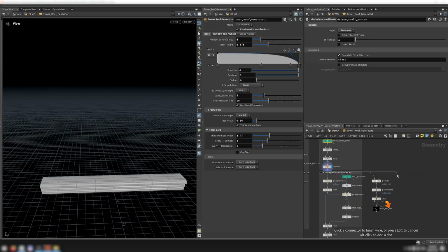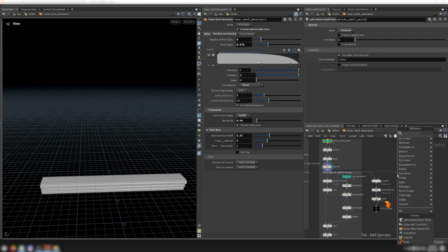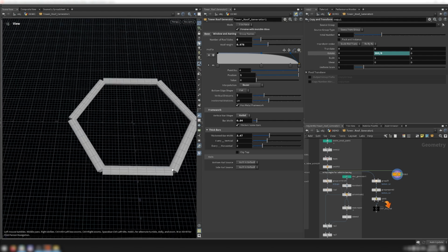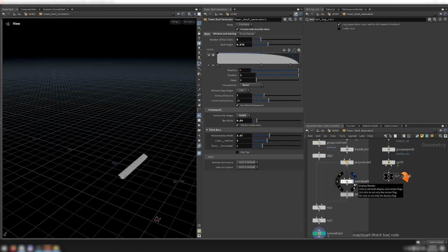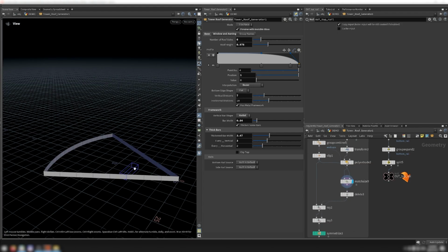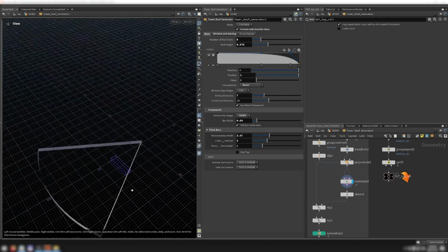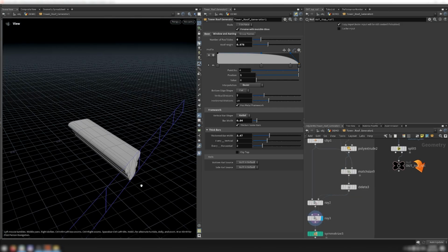If you just sweep the bottom rail, the module looks fine on its own, but when it's assembled, it doesn't line up well. So let me show you what I mean. You can see that the bottom rails are going to leave gaps between each other. In order to remedy this, I create a slice of geometry with the angles that will tile correctly, and then I project the edge of the bottom rail onto that geometry.